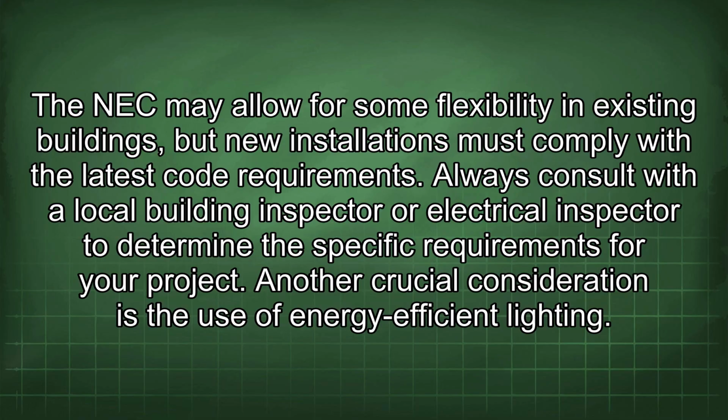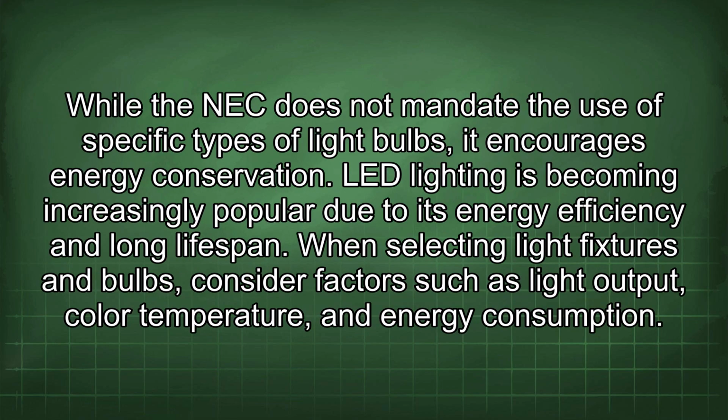Another crucial consideration is the use of energy-efficient lighting. While the NEC does not mandate the use of specific types of light bulbs, it encourages energy conservation. LED lighting is becoming increasingly popular due to its energy efficiency and long lifespan. When selecting light fixtures and bulbs, consider factors such as light output, color temperature, and energy consumption.